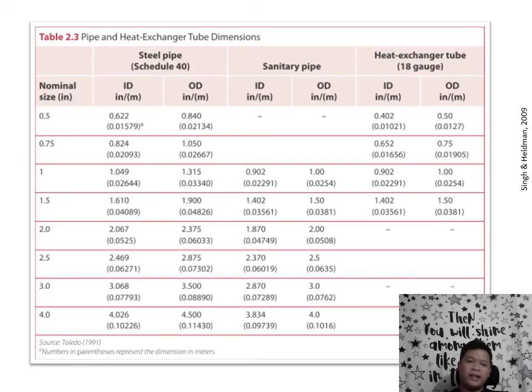So this one is just a throwback and a reminder that whenever you are dealing with problems in fluid flow, you always check first ano yung type ng pipe and then refer to this table for the internal diameter. Kasi sabihin sa'yo mamaya, a 1-inch nominal sanitary pipe, tapos bigla ka nag-assume ng 2.54 cm internal diameter when in fact, based on this table, it's 2.29 cm pala. Di mali ka na agad sa first step pa rin ng calculation mo. Okay? You have been warned.